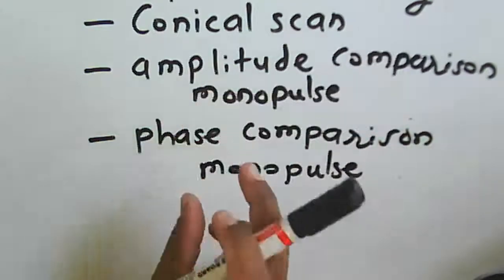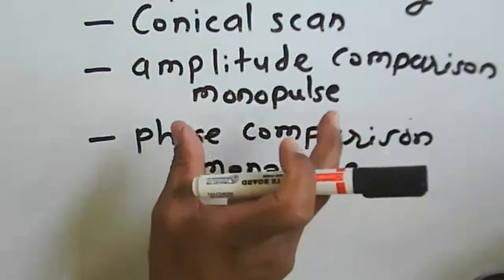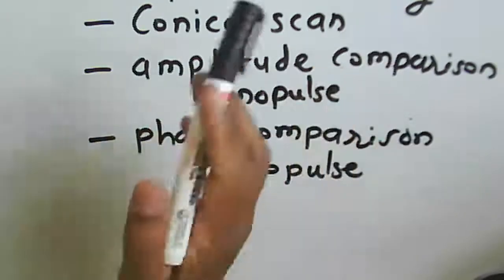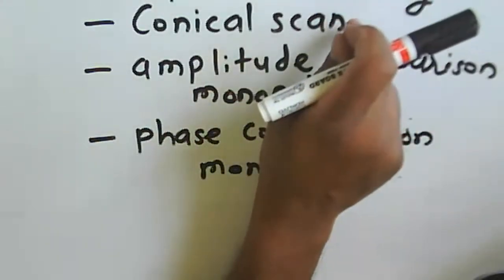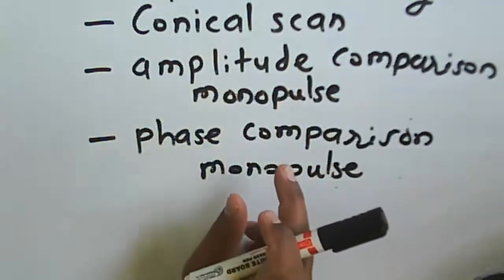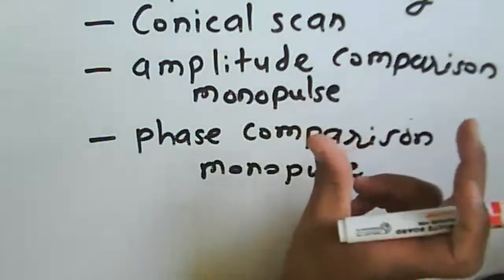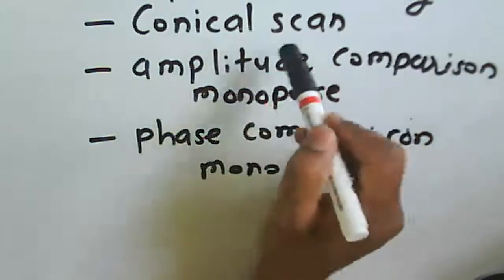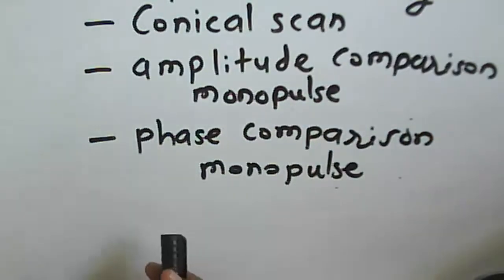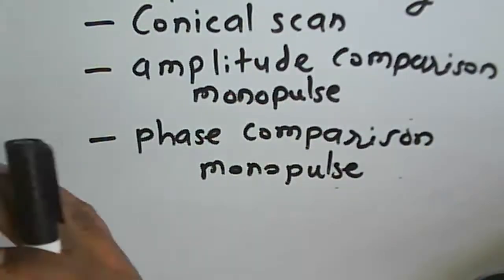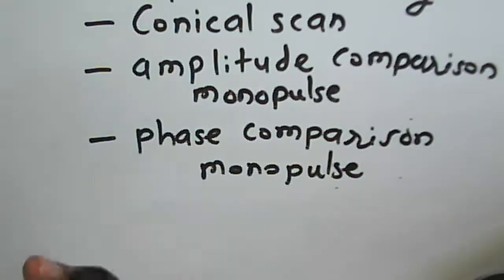And then for the rotation, if you use monopulse tracking, the rotation speed of the antenna beam is very low as compared to the conical scan. Monopulse tracking requires a single pulse, because we use two antennas and a single pulse is to be sent. But in the case of conical scanning, we are supposed to send a minimum of 4 pulses to scan the given radar. That means with a sequence of pulses we can find out the coordinate there. So we measure the angle as well as the range through this tracking system.